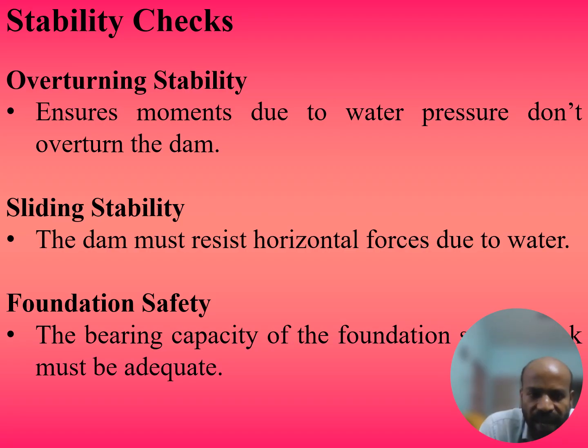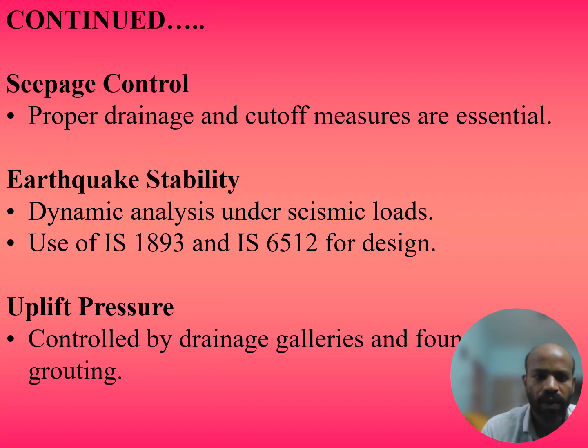Next, sliding stability. Here, the lateral force is mainly due to the water. The lateral load leads to the sliding of the dam. The lateral load is resisted by the frictional force induced between the dam and the underlying soil. Next, foundation safety. Here, the soil pressure due to the vertical load should be less than the safe bearing capacity of the soil.